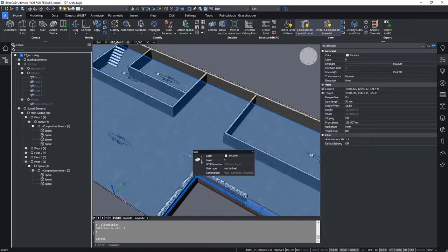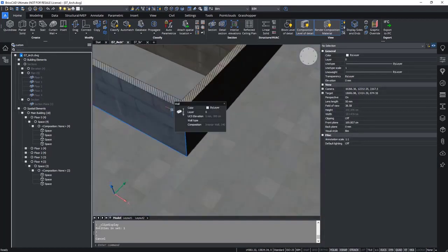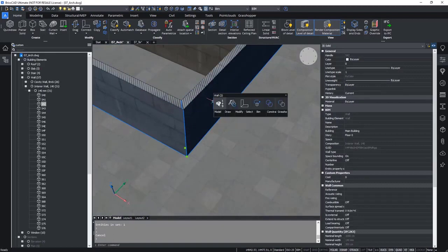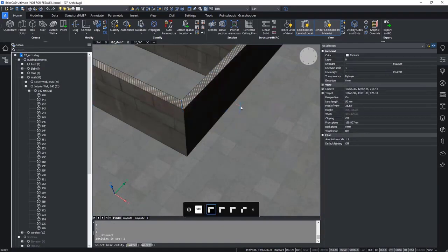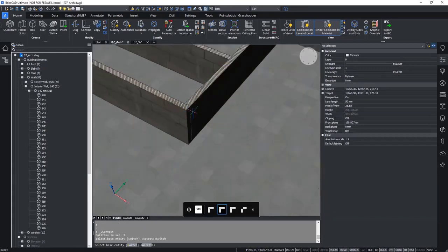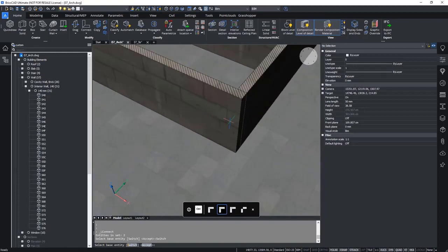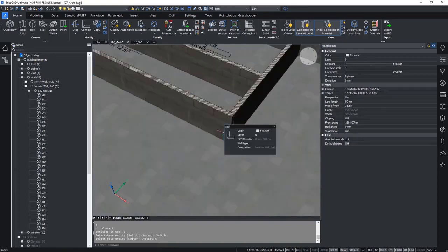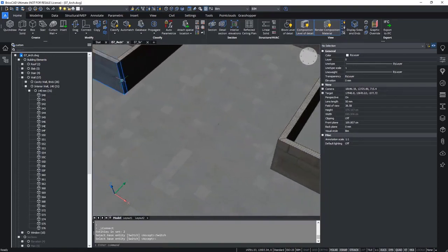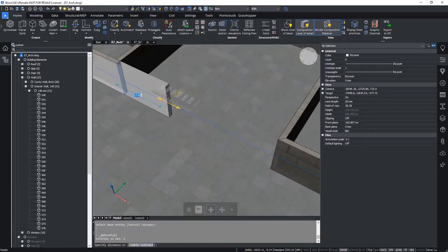Okay, as soon as we did that, I will DM push pull this face after L connecting, so that I can create a different L connection. So I want to create an L connection so that I can extend this wall to the next part, so I do enter. Then we highlight the end face of this wall, and I can DM push pull it.